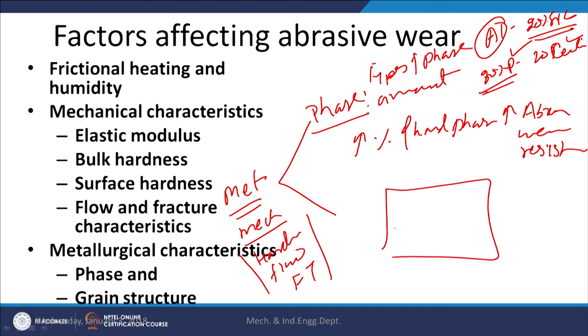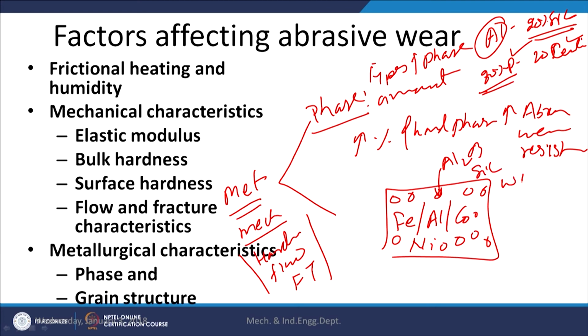Soft metal matrices like iron, aluminum, cobalt, and nickel are soft and comparatively tough. So, efforts are made to reinforce hard particles in the matrix of the soft material so that their resistance to abrasion can be enhanced. It can be in the form of reinforcement of Al2O3, silicon carbide, tungsten carbide, etc., as per the purpose and compatibility.